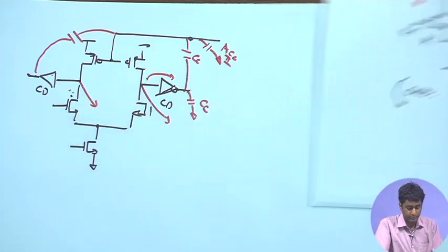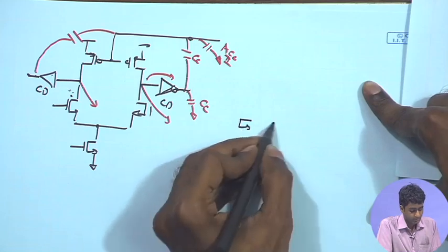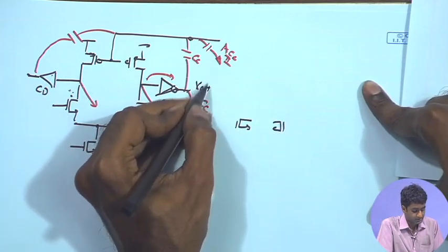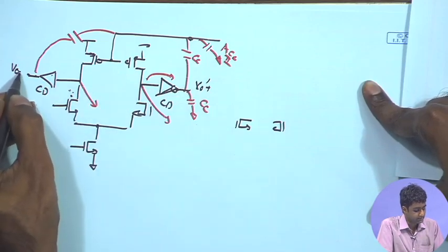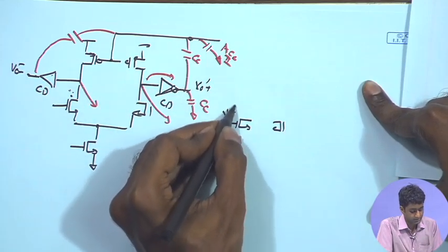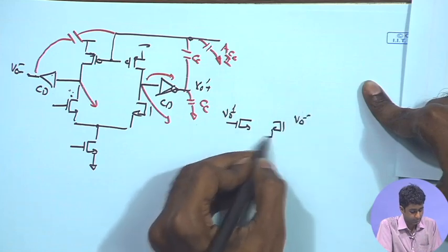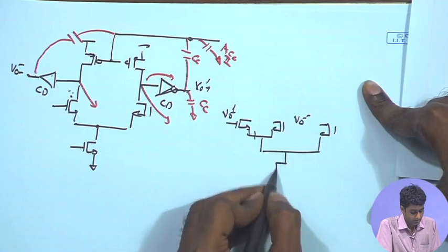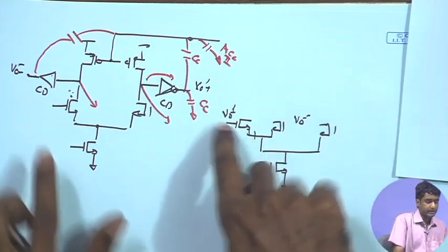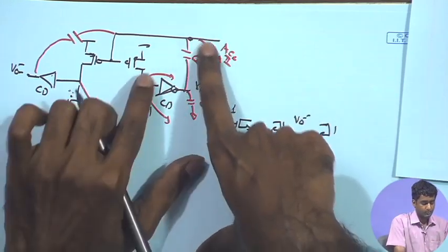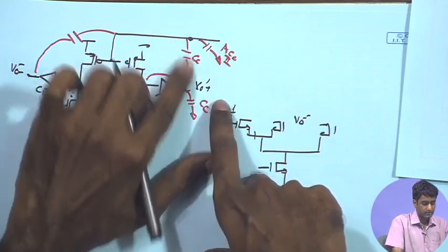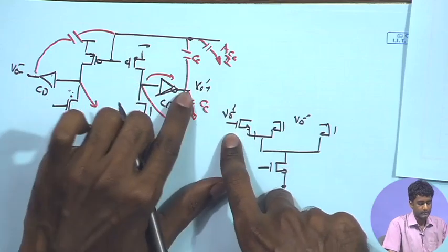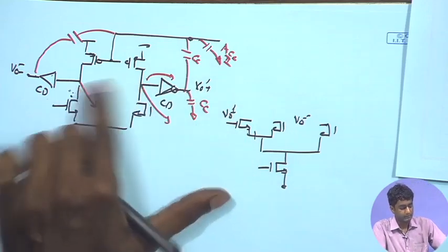So, after that you have your normal error amplifier operation where the two outputs VO plus dash and VO minus dash now will be going. This is your error amplifier that you had earlier. So, in that case the Cc has been decoupled from the output node, that is not influencing the differential node as such.